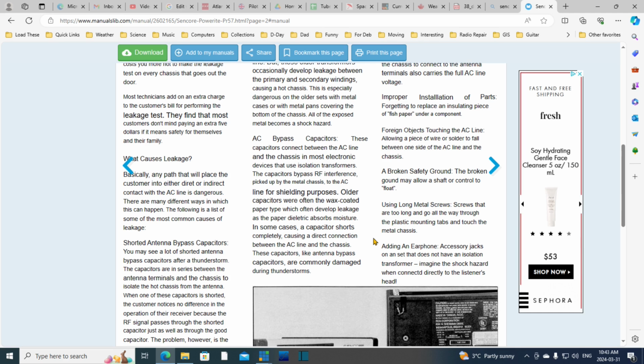But now you've introduced something called step potential. Step potential, picture yourself standing outside the fence, maybe looking up at the beautiful tower and appreciating the wonderful history of electrical distribution. And you happen to lean onto the fence. So you're standing about a meter away from the fence, and you put your hand on the fence.